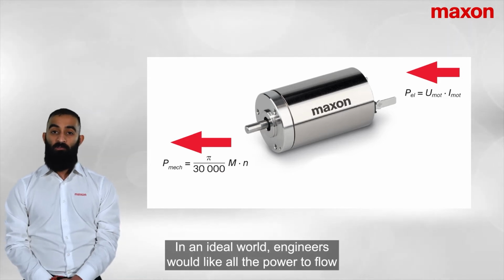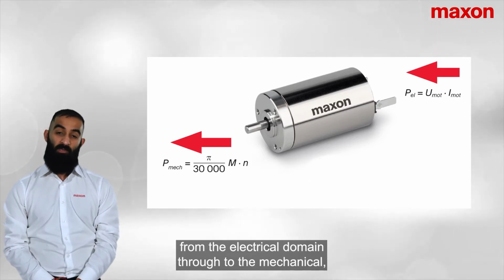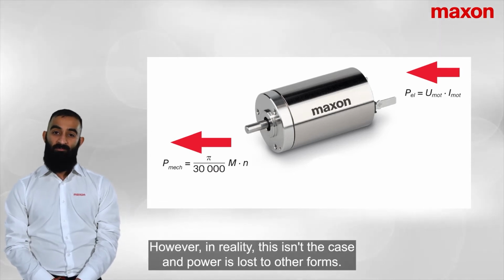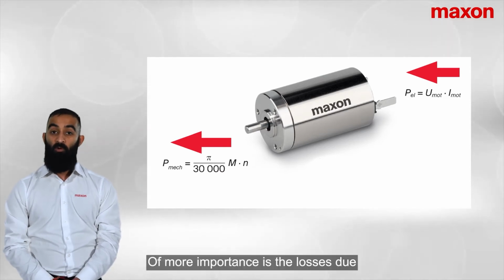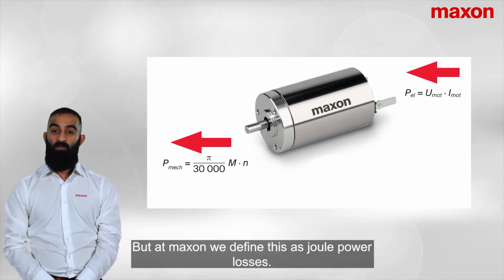In an ideal world, engineers would like all the power to flow from the electrical domain through to the mechanical, thus utilising all the power available at the input. However, in reality, this isn't the case, and power is lost to other forms. This may be due to the friction from bearing elements and brush elements, but this is often neglected. Of more importance are the losses due to the winding, sometimes known as copper losses, but at Maxon we define this as joule power losses.